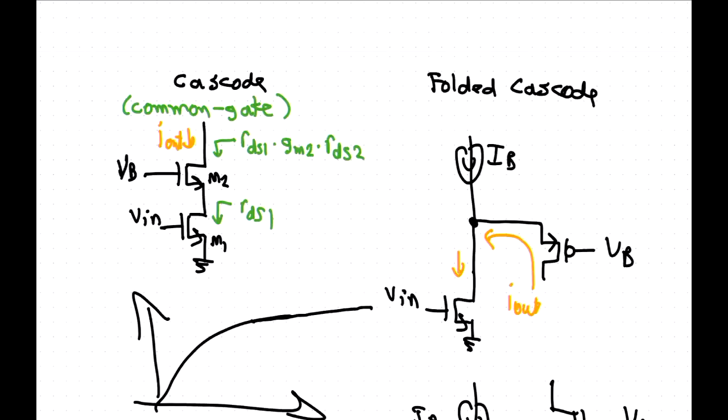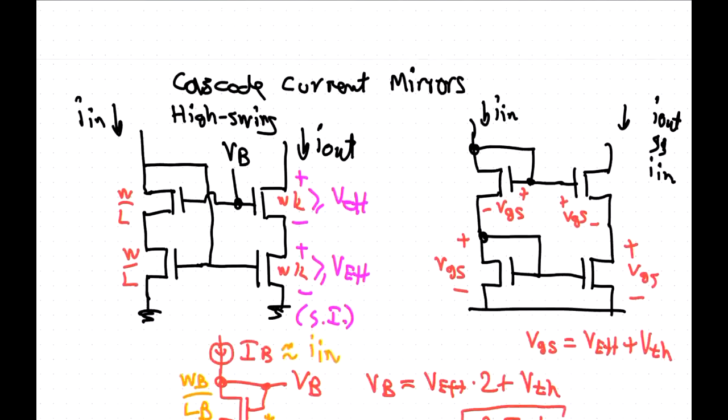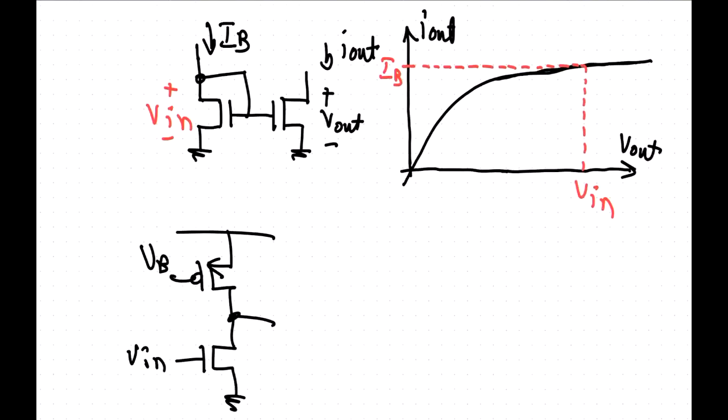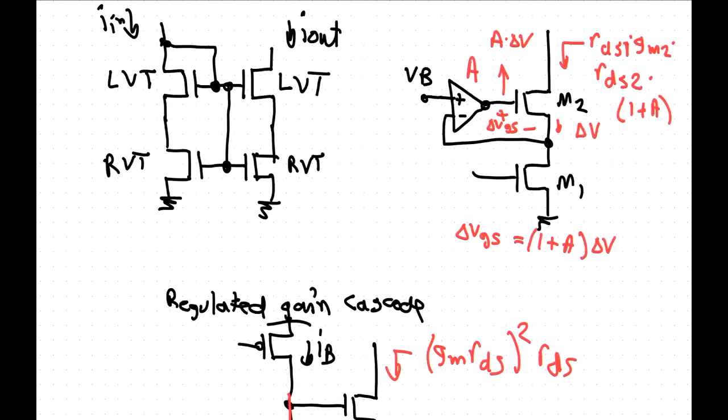Okay, so what did we do last time? We looked at cascodes, telescopic cascodes and folded cascodes. We looked at how to bias the cascode, so high swing current mirrors and traditional current mirrors. We also looked at using different kinds of threshold voltages in order to make sure we can have a self-biased current mirror and not use up too much voltage.